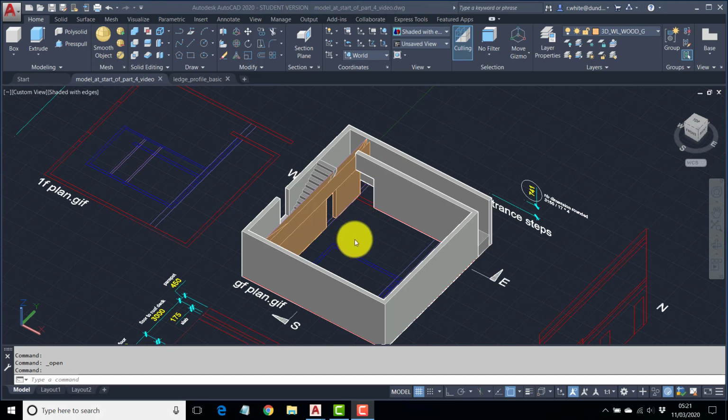This is the state of play. We've got the outside walls done, the staircase is done, and we've used a couple of different techniques to model the timber dividing wall between the dining and the staircase. Used thicknesses on one side and 3D faces on the other side, and 3D faces to cap the gaps inside the doorways. Okay, we're going to look at this material now.